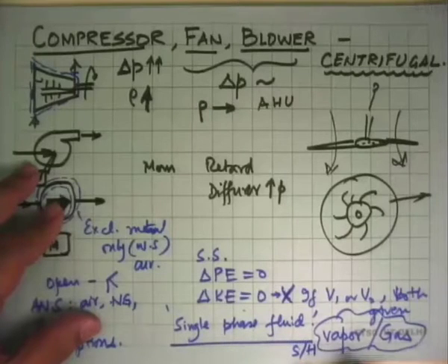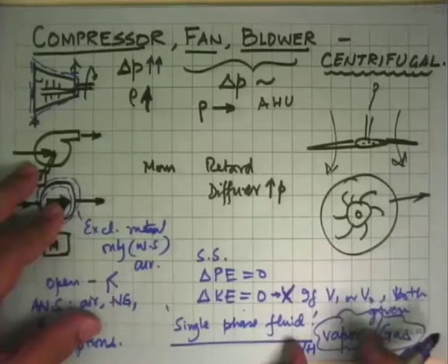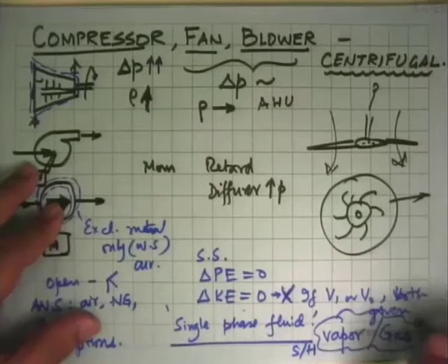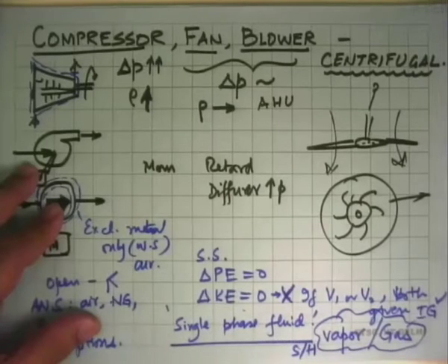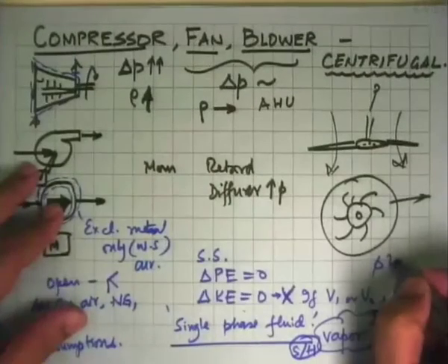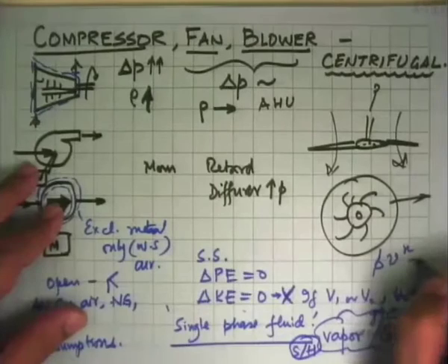And it could be possible to assume ideal gas behavior; if it is like nitrogen or oxygen, in that case, ideal gas behavior is okay. Otherwise, like in a refrigeration system, we will have to go to the property tables and get the data from there. Nevertheless, this process can be approximated by something like PV to the power n equal to constant.